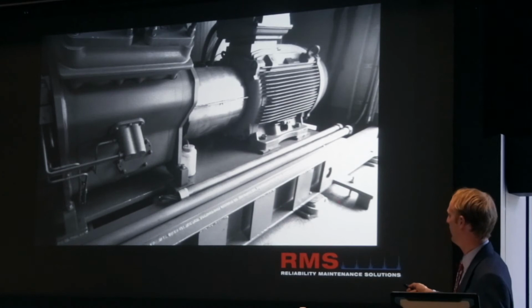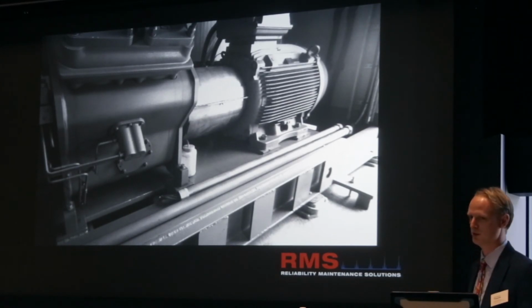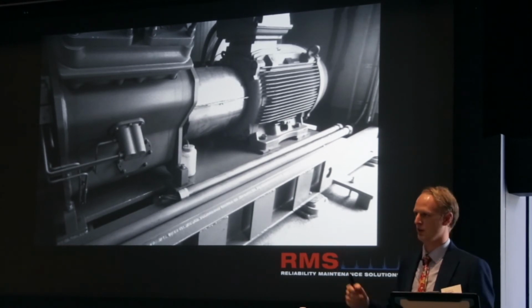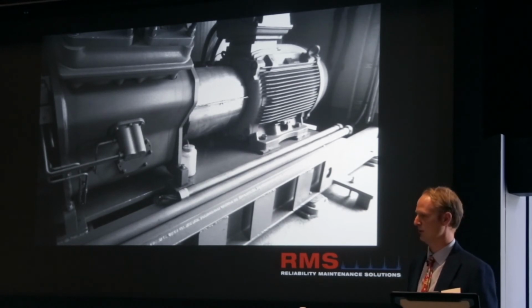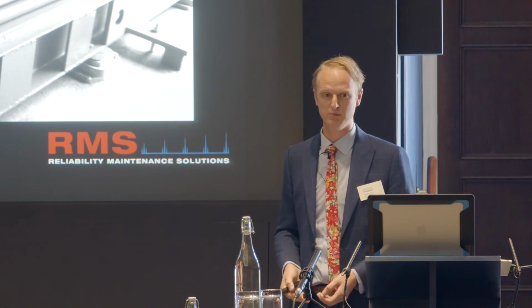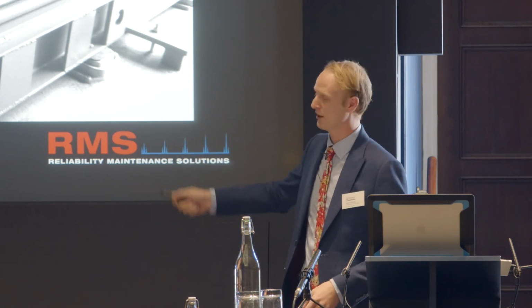However, there's still an inherent issue where these anti-vibration pads are generally used on these type of machines for reduction in vibration levels on suspended floors, but we're on a solid concrete base. Why would we want to try and dampen that using those pads when we can build a good base for that machine, throw away all the steel work and have it nice and solid on a good concrete base?